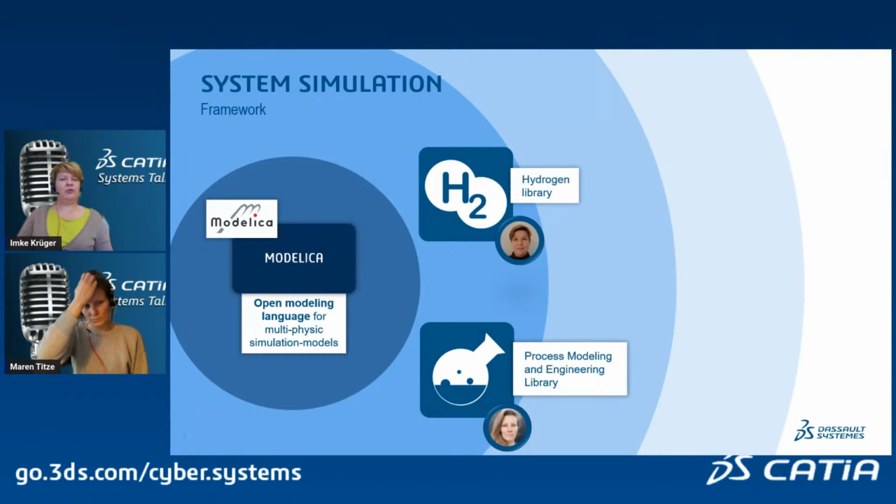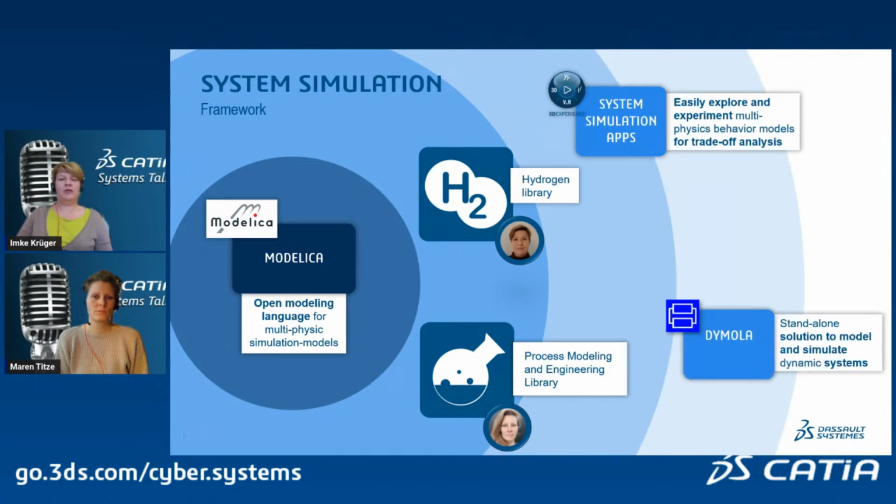We write components in the Modelica language, and they are then structured into packages that contain different components in order to model the systems you want to model. In order to be able to simulate the models that you build of the system, you need a simulation environment. You can use, for example, Dymola for this. That's an environment where you can also write your own components and implement further libraries.